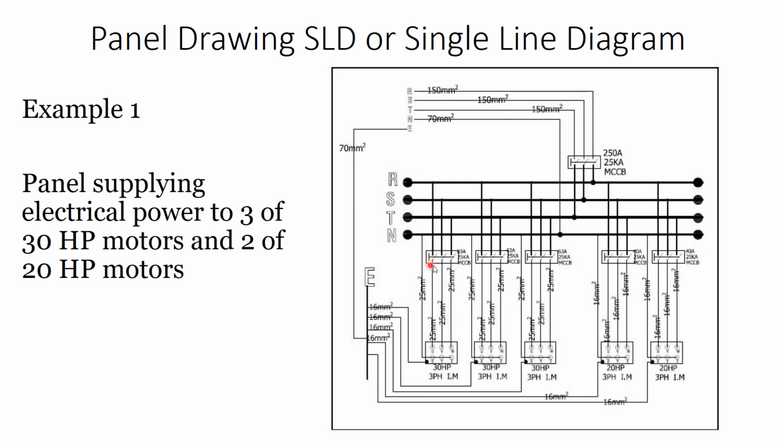So you will see that this is a circuit breaker which protects the motor, with 63 ampere as the rated current and 25 kiloampere as the short circuit current. This is a molded case circuit breaker. You can see that it takes the R, S, and T going to the circuit breaker, and we have here R, S, T going to the motor, and finally the neutral.